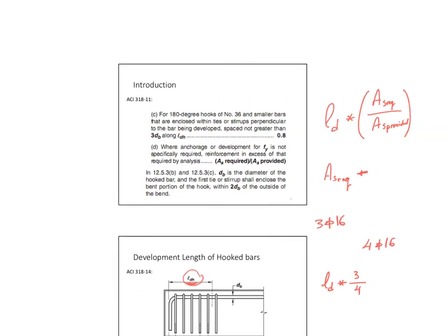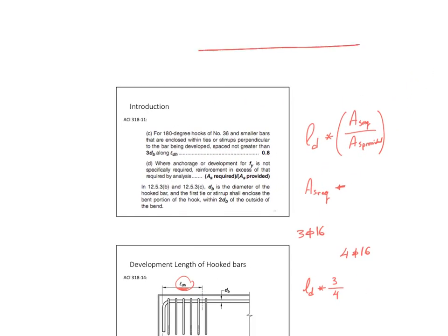Let's remember something important on this. My LD is the required length to develop the stress in the bar. Am I pulling from here? Here. I'm pulling here. Tension that will make my stress go all the way up to F yield. This is where I'm yielding this bar. True? The stress at the very first point equals what?